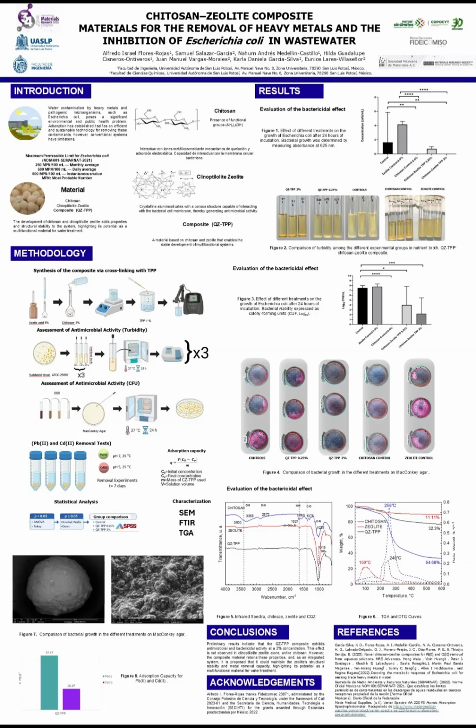Chitosan exhibited a marked loss at 256 degrees Celsius, associated with its thermal and oxidative decomposition, as well as with the vaporization and release of volatile products. In contrast, the zeolite showed only a loss of residual moisture in its pores, confirming its high thermal stability up to temperatures below 600 degrees Celsius. The composite, meanwhile, exhibited weight losses corresponding to both moisture evaporation and the degradation of the organic phase of the chitosan.